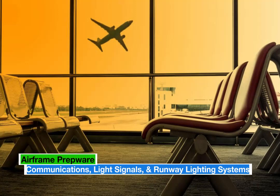How may the operation of an installed emergency locator transmitter, ELT, be verified during aircraft inspection? By tuning a communications receiver to the civil emergency frequency and activating the ELT momentarily within 5 minutes after the hour. A radar altimeter determines altitude by transmitting a signal and receiving back a reflected signal.